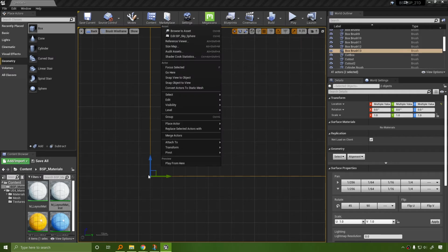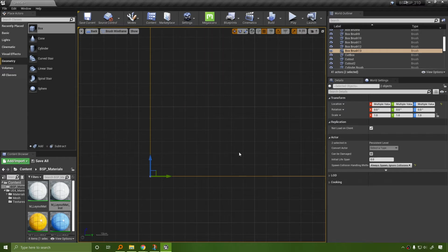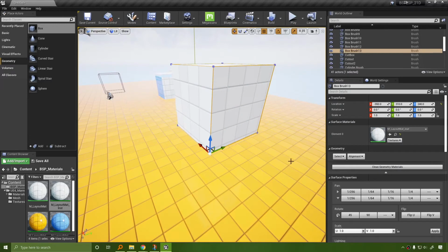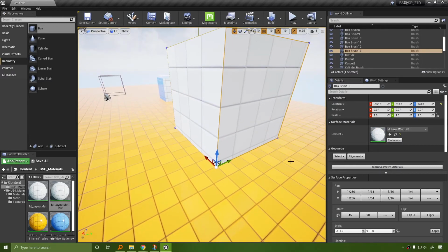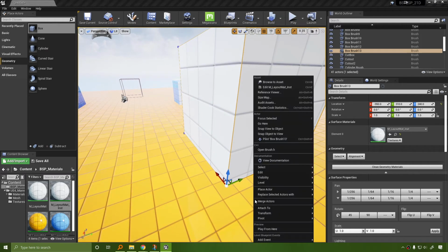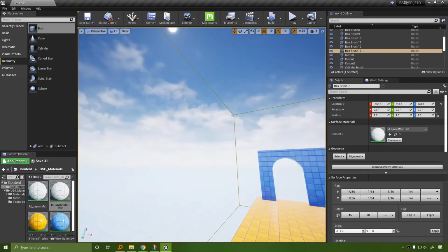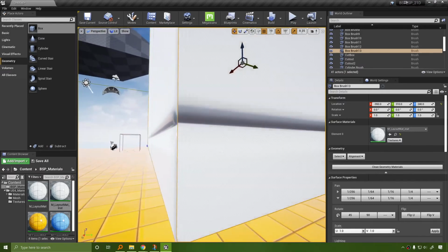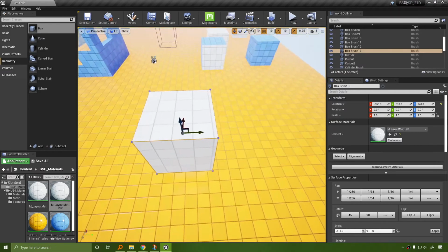I'm going to right-click the corner, move off of it, right-click, and then I'm going to set the pivot offset here. Actually, you know what? Let's set a pivot offset. So when we go back into our perspective view, our pivot is now permanently set. Set pivot offset here is just temporary. So what we have done is, let me right-click pivot, let me reset it. It's a little bit harder to do it in perspective mode because, as you can see, it's very chintzy and kind of weird to try to get that selected.